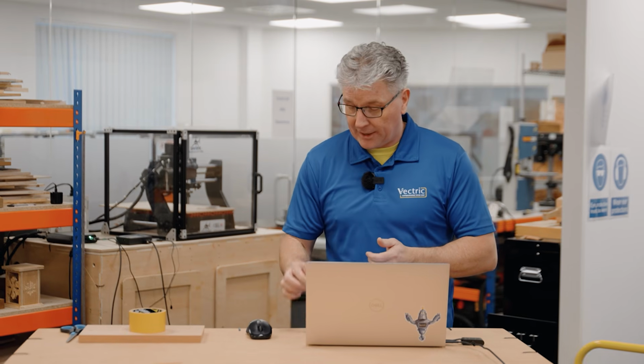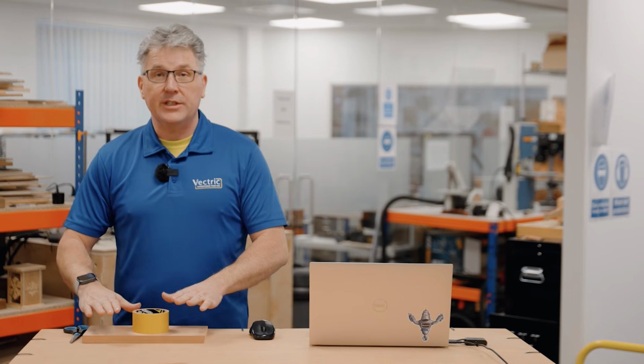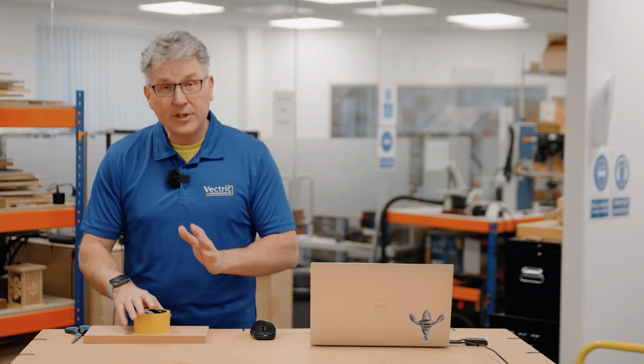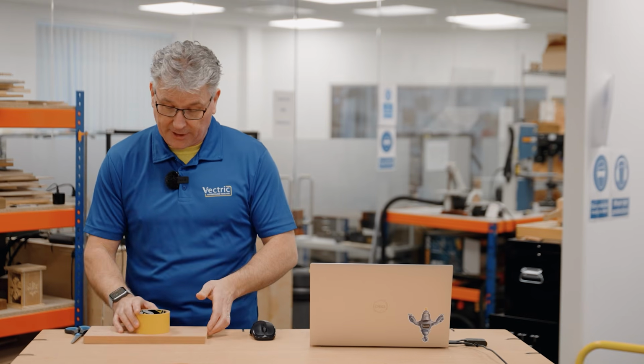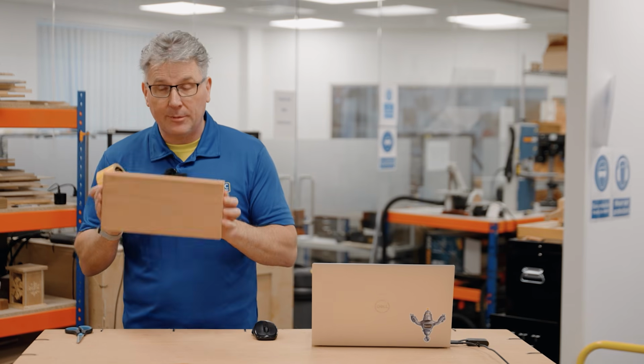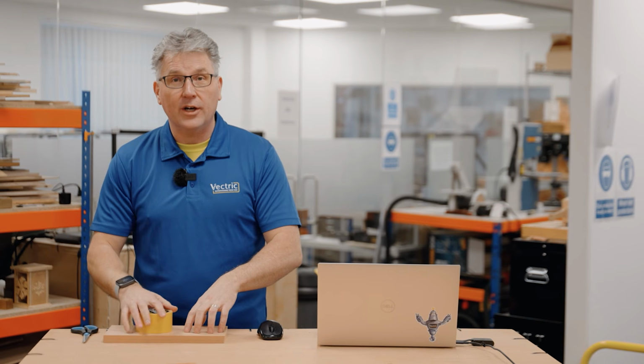But before we do all that, I'm going to need to go ahead and prep my material so that I can fixture it down to the CNC bed in a safe way. And so the best way for me to do it for this machine at this current time is use some double-sided tape, really strong double-sided tape on the back of my material, and I can just go ahead and stick that down. So I'm going to prep that up and get it on the CNC machine.